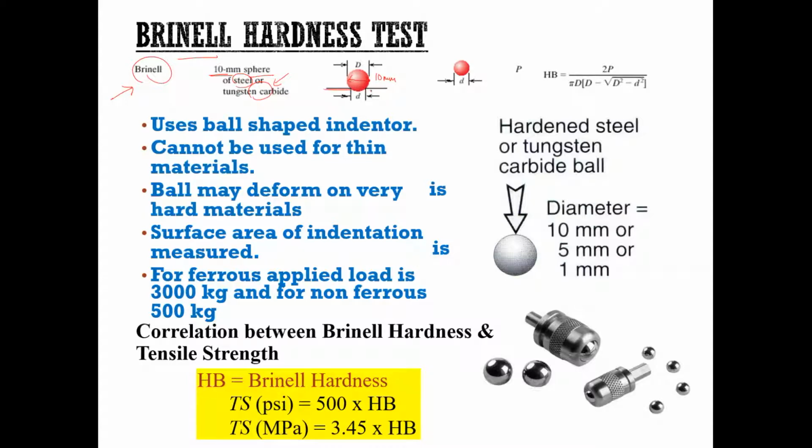Alright, say this is your sample, the surface of the sample, and this d value is the indent that we create during the hardness testing. So this represents that. This is the top view, and this is the side view. If your material is very hard, the amount of indent will be less, so the d value will be less. So your material is very, very hard. If your material is soft, then the d value would be larger.